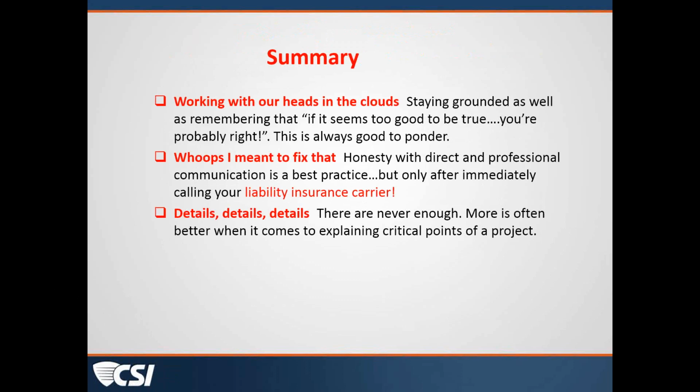A couple of closing comments from me on the details issue. There was a time years ago when we would draw axonometrics in the construction documents for complicated intersections and connections to help explain them. I would suggest that if you've got a situation like that where that information would be helpful, go ahead and include it in the documents. We've done that on projects here recently. The flat 2D section cut, plan cut detail that you draw may not provide enough information, and doing a simple axon could be a world of difference.